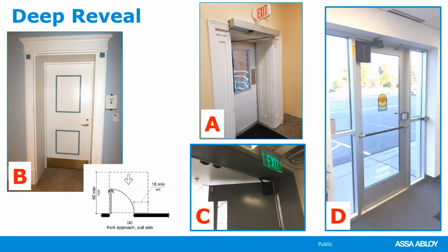And sometimes you would need an output shaft extension in order to move the door arm downward enough to clear the door stop and the framework, as you'll note in picture D. If you were not using a door-mounted operator, and if the operator were mounted overhead, you would have to extend the output shaft down probably about 8 inches to 10 inches in order to clear so that the arm would not hit the reveal when the door was opening and closing.